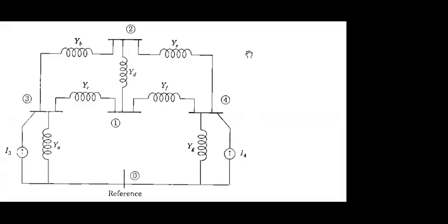Regarding the nodal equation writing, try to write the voltage terms on one side and the current, if there is any current source, on the other side of the equation. The equation is okay, but you have to write it in a form so that when we want to form the matrix, it will be easier. Only the current on the other side.